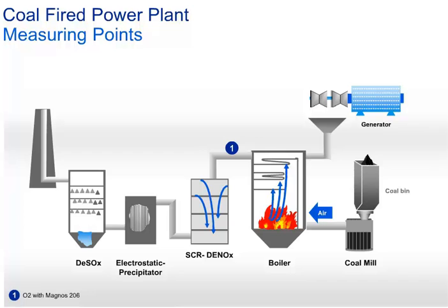Efficiency of DNOx process. Nitrogen oxide and nitrogen dioxide are a major cause for environmental damage. These components are removed by injection of ammonia. The injection of ammonia is regulated via the NO/NO2 concentration in the exhaust gas. The efficiency of this process is controlled by monitoring the outlet for excess ammonia. Analyzers used are infrared photometer for NO, or alternatively ultraviolet photometer Limas for NO and NO2, and laser analyzer for NH3 measurement.